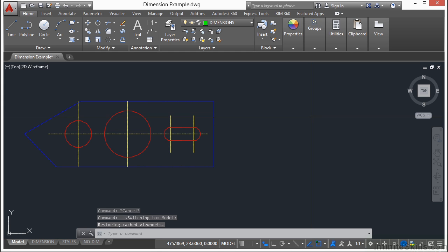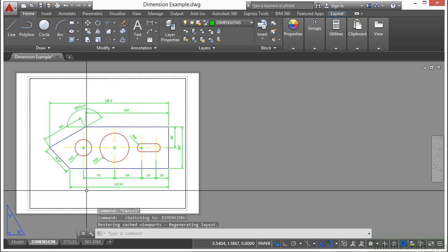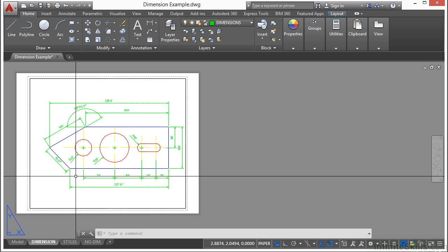on the button there. Now, typically, a model composed of geometric objects is created in a three-dimensional space called Model Space. That's what this is here. A final layout of specific views and annotations of this model is created in a two-dimensional space called Paper Space. That's right here. These spaces are accessible on two or more tabs near the bottom of the drawing area. The Model tab and at least one other Layout or Paper Space tab. Oftentimes we'll refer to these as Layout tabs or Paper Space tabs. They mean the same thing.